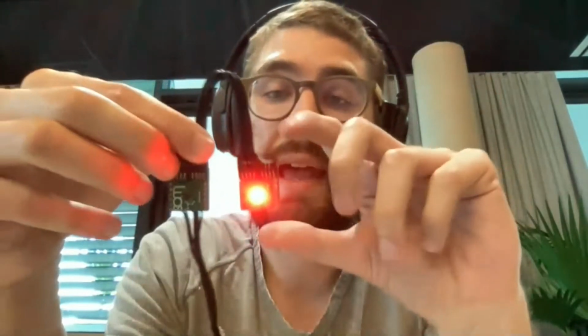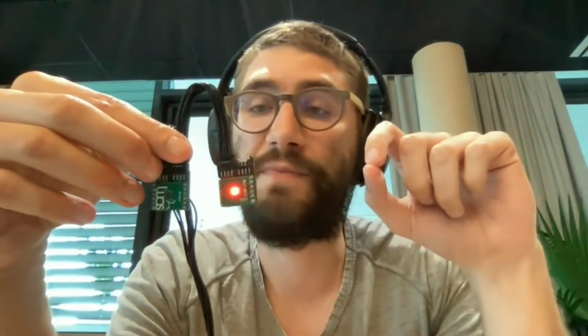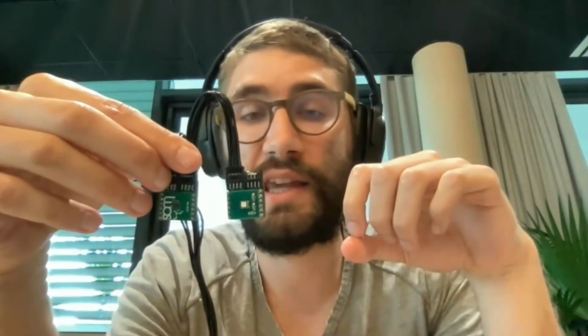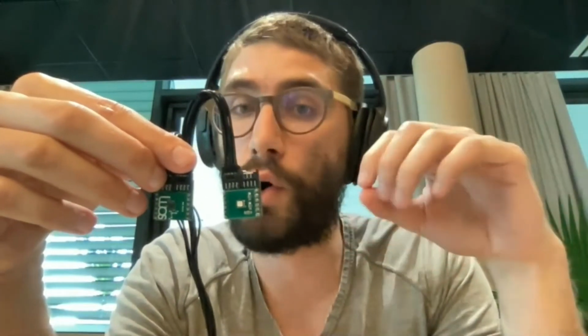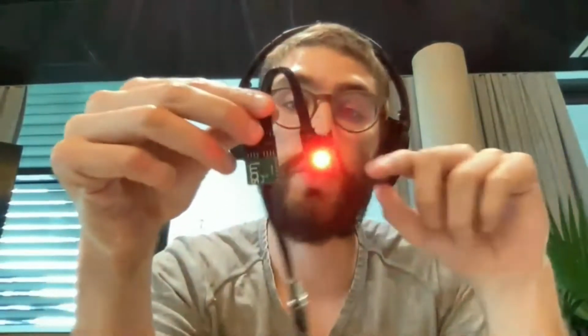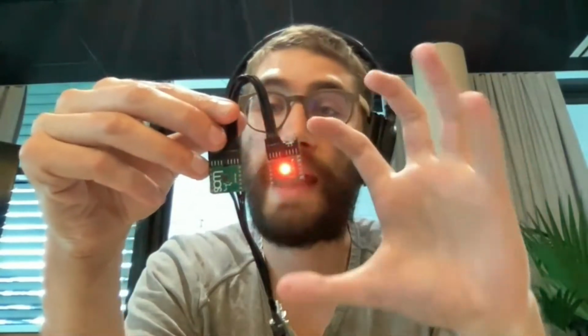The application on the LED here makes something we call a detection. This detection allows Luos to detect the physical position of each board in the network. Based on the position of all the boards, we distribute a unique ID to all the services on the network, and we regroup all that information into a structure we call a routing table. And we share this routing table with all the boards on the system. So now all the boards know all the services available in the entire system and can use them directly.